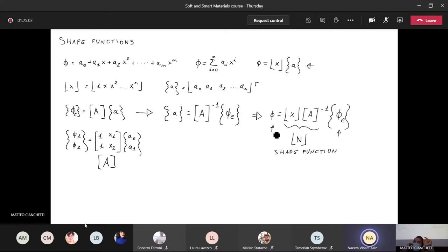I was wondering if the shape function is only about the bulk of the material, but not the exterior surface. Well, it is not a matter of the inside or outside of the material. The shape function is only a mathematical interpolation of the result you got from two nodes, or at least within one element. We only saw examples with elements with two nodes, but whatever the number of nodes, the shape functions take care of what happens in a single element.